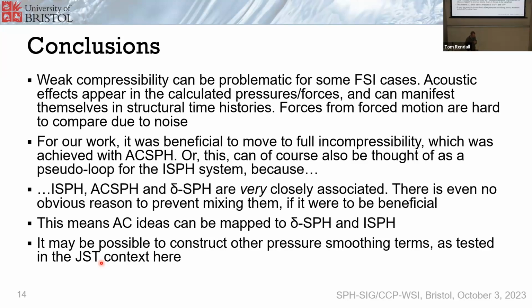By pseudo time, do you mean dual time step? Yeah. I didn't really talk about the integration very much, but yes, the pseudo time, or dual time effectively. So the AC part is in the pseudo time or dual time part, and then the real time integration. It's important to separate that out. You could do that wherever you wanted, right? The integrator is not linked to artificial compressibility, but we did a second order backward difference, which is fairly consistent with what people use for finite volume methods. But you could use any other integrator if you wanted, of course.